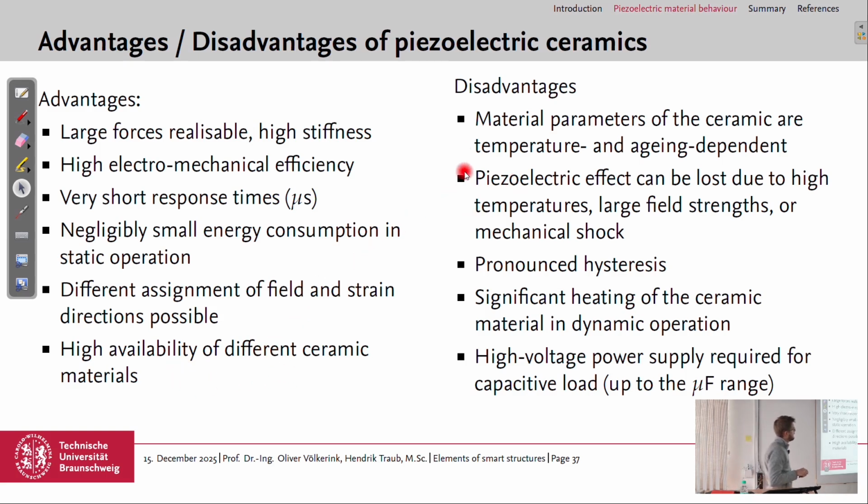And disadvantages are the temperature-dependent behavior. Even in, let's say, the normal temperature range, it's also negligible. We can lose the piezoelectric effect due to high temperatures, the Curie temperature, due to large field strength, so going above Emax, and also due to mechanical shock.